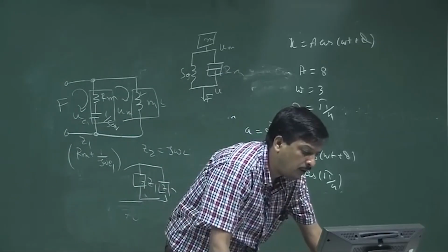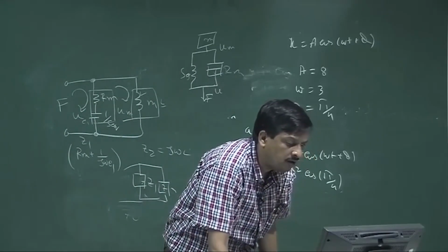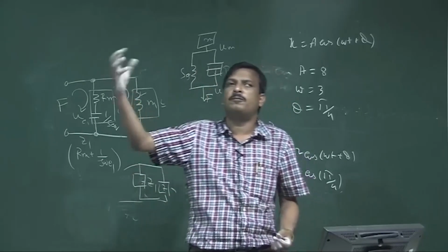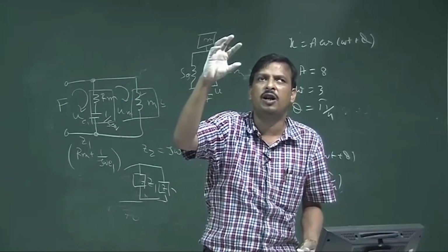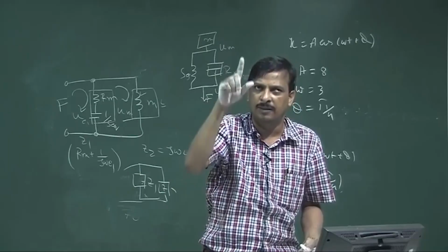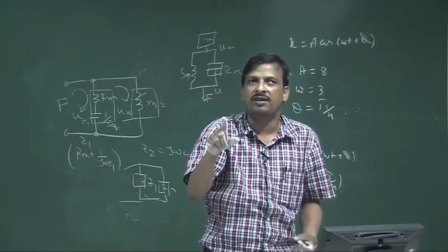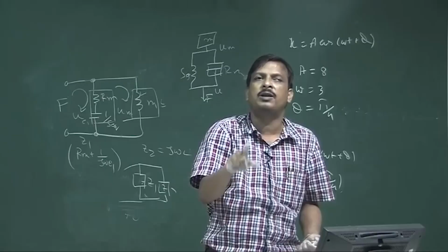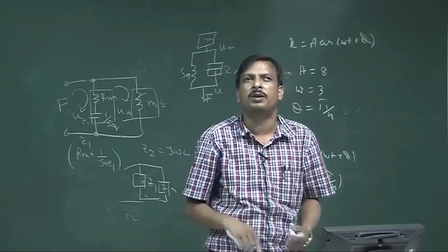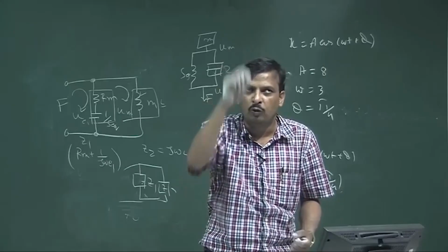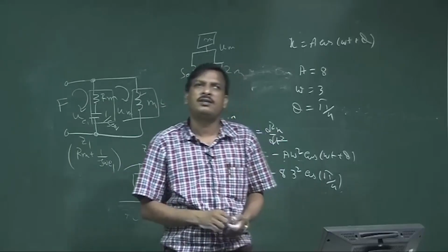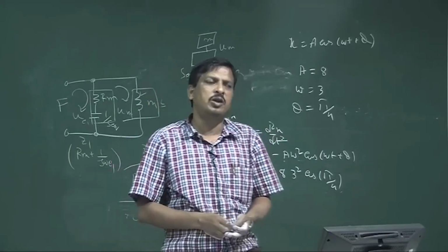So, this kind of problem people may give you. Suppose this is a loudspeaker diaphragm, the mechanical resistance is given, the stiffness of the diaphragm is given, the mass of the diaphragm is given, and how it is housed is also given. So, you first draw the equivalent mechanical circuit, then you can convert the mechanical circuit to an electrical circuit. Okay. So, that way you can do it.